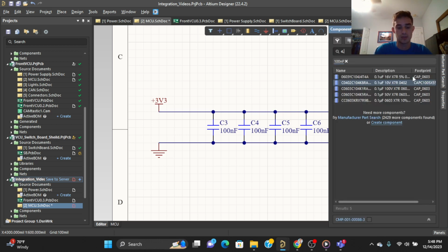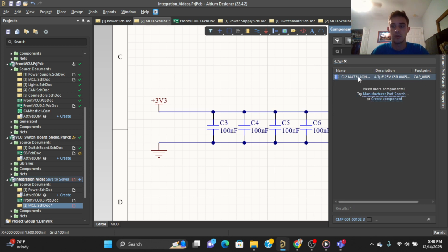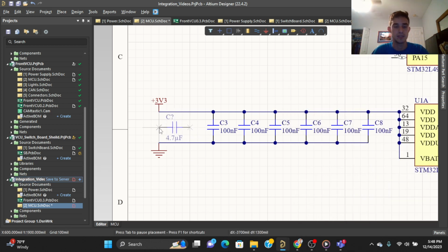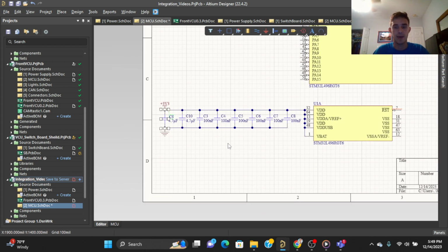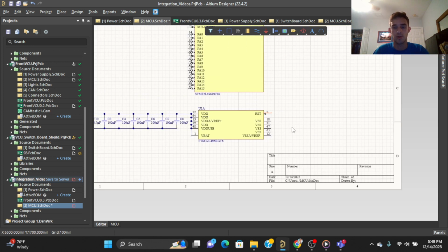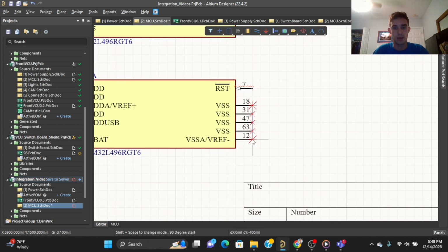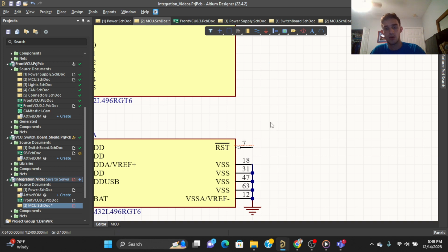Components 4.7 UF. I'm going to go ahead and place these. These are going to be pretty large 0805 capacitors. And I'll move that out a little bit. There we go. And this will be C10 and C9. Okay. So there's our bypass capacitors, providing power to our microcontroller. These guys are all ground pins, so that's the easiest part to route up. Oops, ground. Amazing.